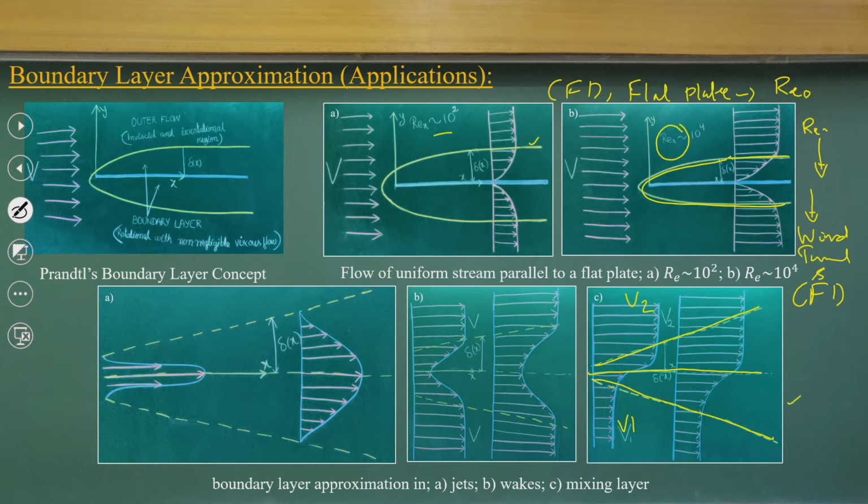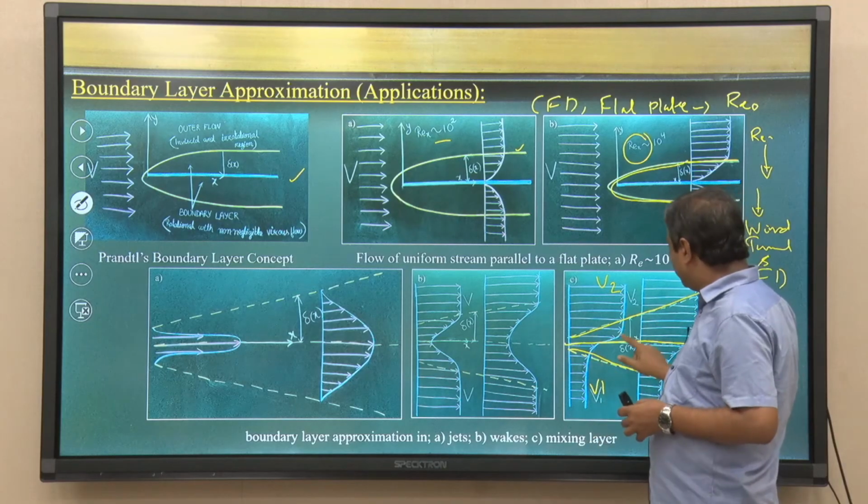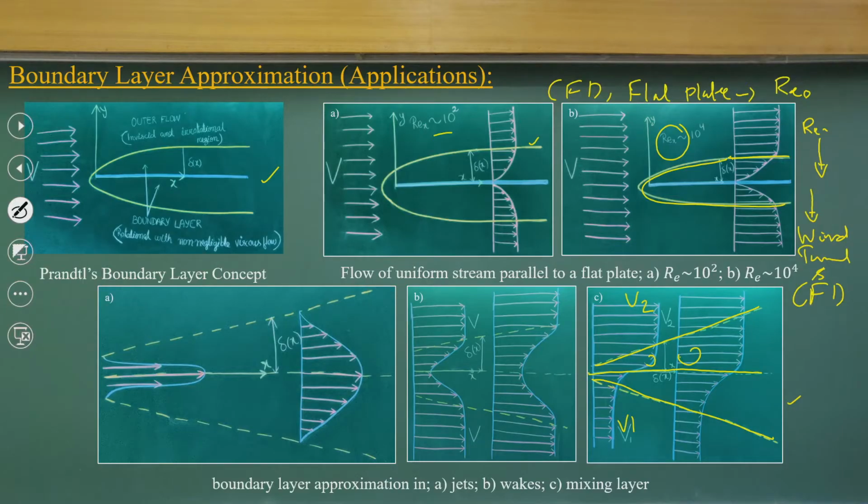Okay. So, this is a visible boundary layer, which we can always look at and see, but here two fluids are moving with V1 and V2 velocities. At the interface we will have boundary layer formation which is not visible to us. But in the same way, laminar and turbulent boundary layer formations will happen. So, we can use the boundary layer concept to understand it.